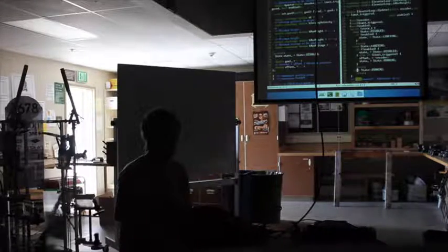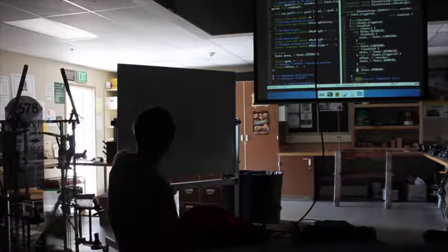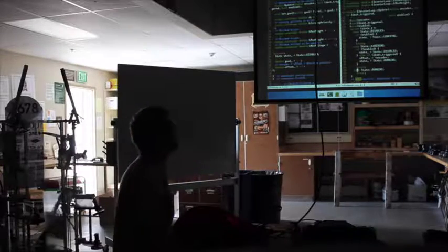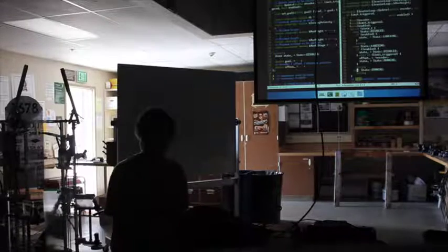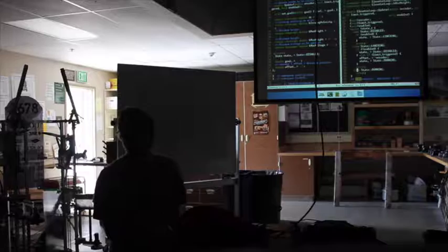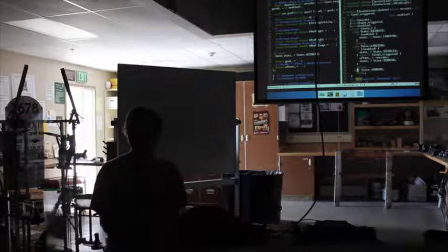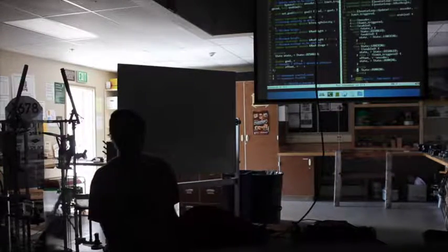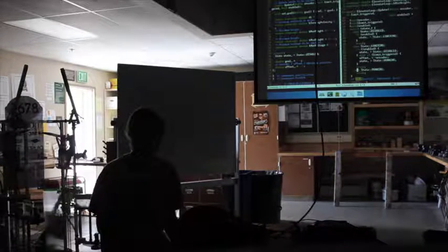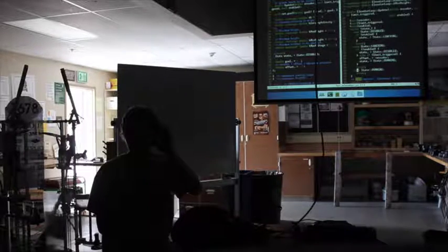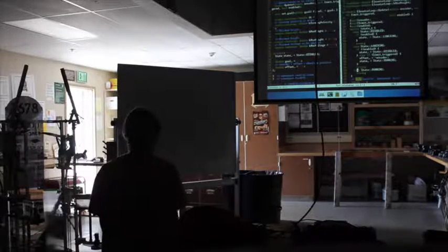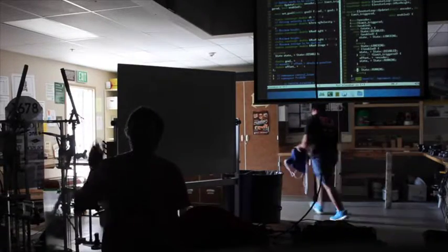There's a bunch of ways we need to change our state, right? Okay, if we're in running, so is that all the arrows? 1, 2, 3. So if we're in running, do we need to do anything? Wait, I have a question. For lowering, don't we have to start lowering it if we're not? Very good. How do you propose we do that? Isn't this the control loop so you can just directly set like the voltage? You're inside the control loop, right? So you can return the voltage. But let's be more controlled than that. I would propose that we tell our control loop to move down at a slow velocity.